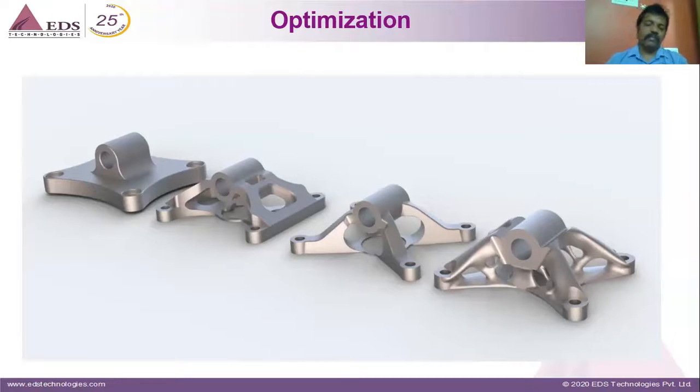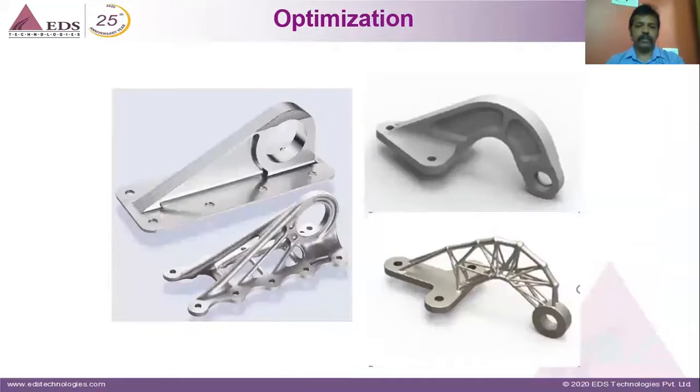Okay, and then we also need to use CATIA and other surface tools to create a proper organic shape, because whatever shape you get out of this FEA tool or the optimization tool cannot be directly manufactured. You will have to make it a little bit symmetric and make some adjustments. So we do some post-processing on that. This is the stage a component has to go through when it comes to optimization.